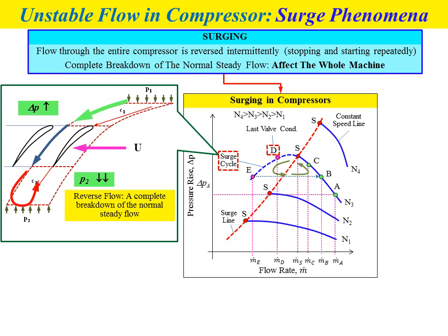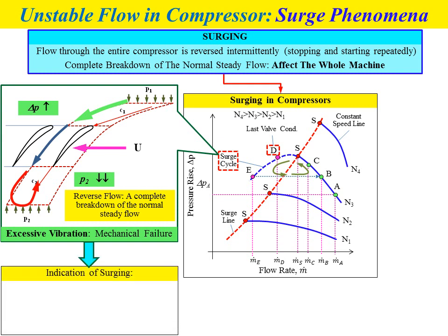This surging phenomena will keep repeating if we do not change the condition of the compressor, and this will cause excessive vibration that further causes mechanical failure.